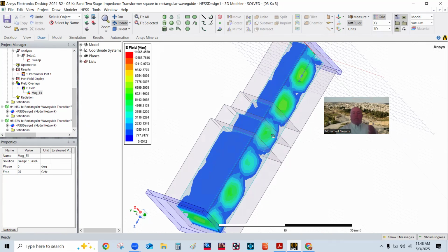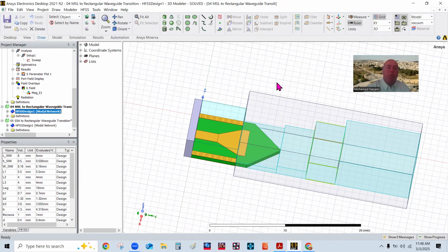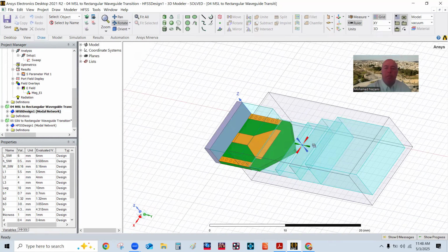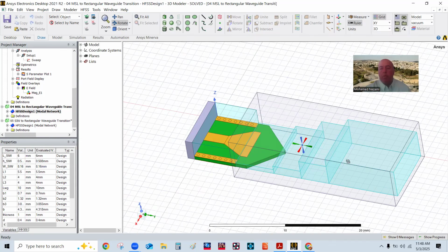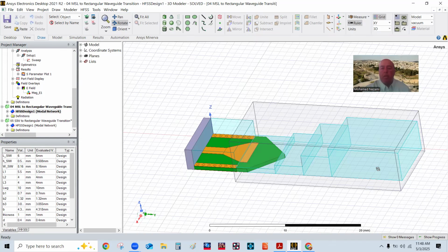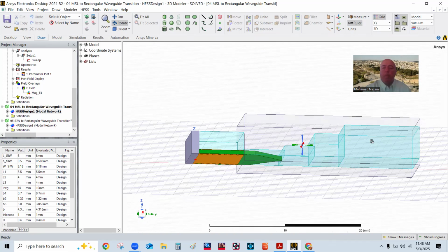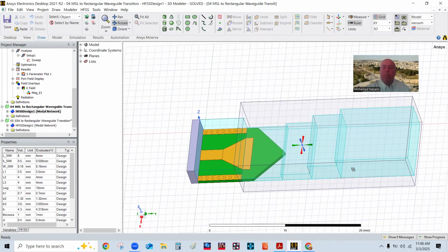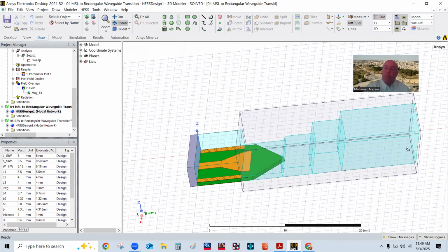All right, so having done this now, so what do we do with this? Well, what we do with this is I'm going to go further and look at two situations that I've already covered in the past, which we want to detail in this case, which are these transitions for an LMB. I want to go from microstrip to a waveguide dimension in here, and I'm going to use a multi-section transformer, a waveguide transformer, to match from this to this.